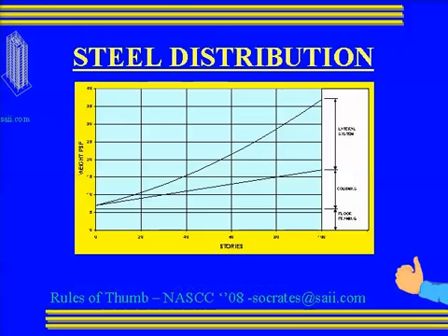Okay, how does the steel get distributed in a high-rise building? The floor framing doesn't change. The gravity, whether it's on the first floor or on the 100th floor, is the same. The columns are essentially going through a linear transformation because as you go higher, you put more load on it relative to the height. And it shouldn't surprise you that the lateral load resisting system is exponential because the loads are of the same shape.